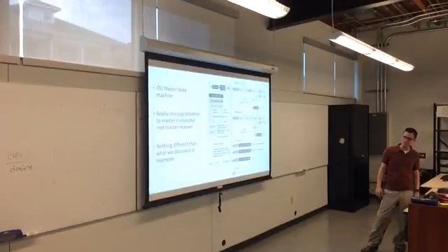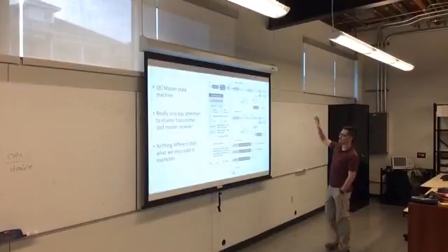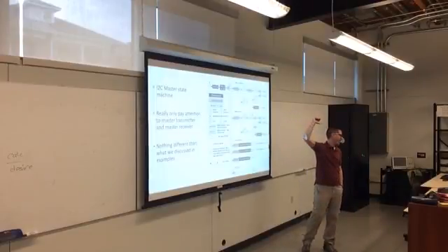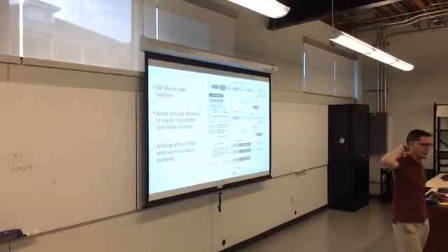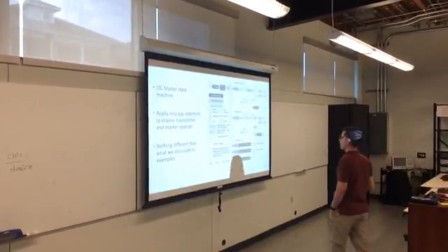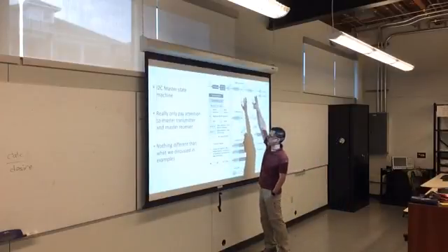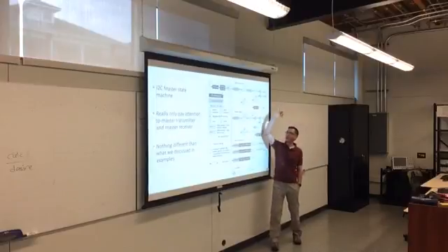This is probably the most important slide. This is probably also the most complicated slide. This is the state machine that governs the I2C bus. So documents produce a set of rules about how devices should communicate. This is the resulting state machine from the master perspective. So the idea is that if you are the master device and you are a transmitter, you have to follow this series of events. And if you are a receiver, you've got to follow these.